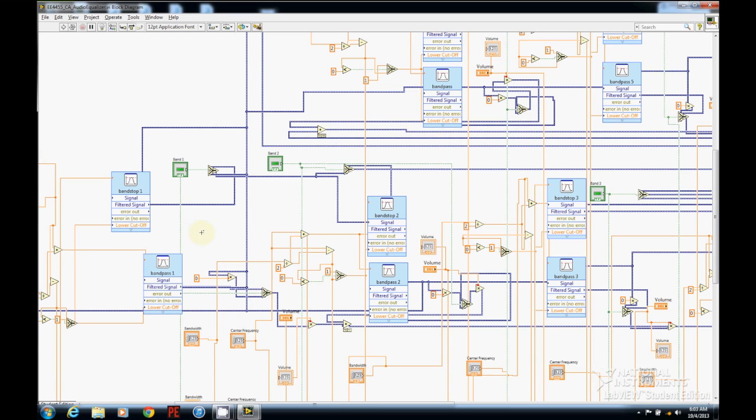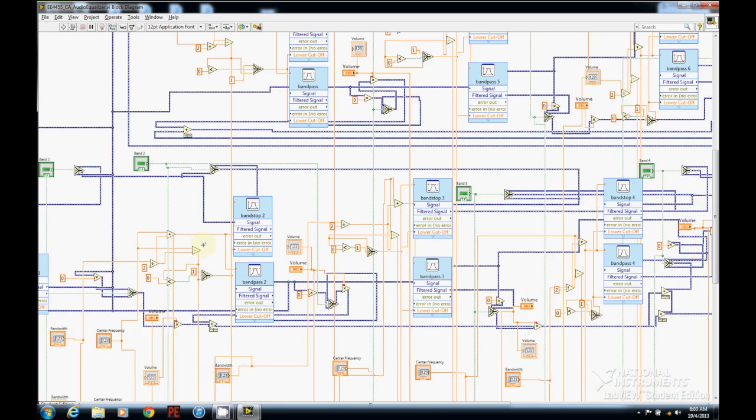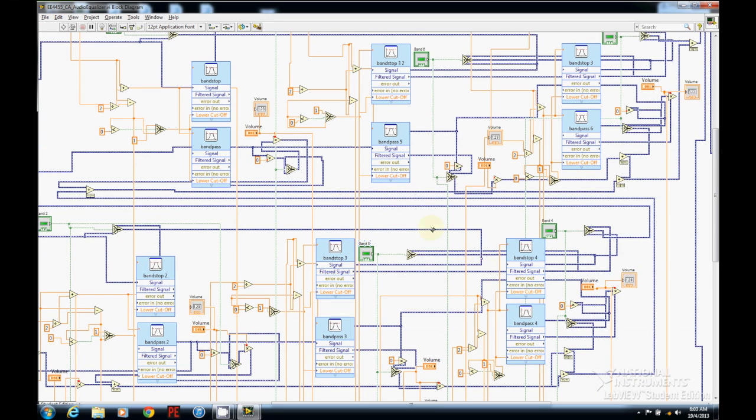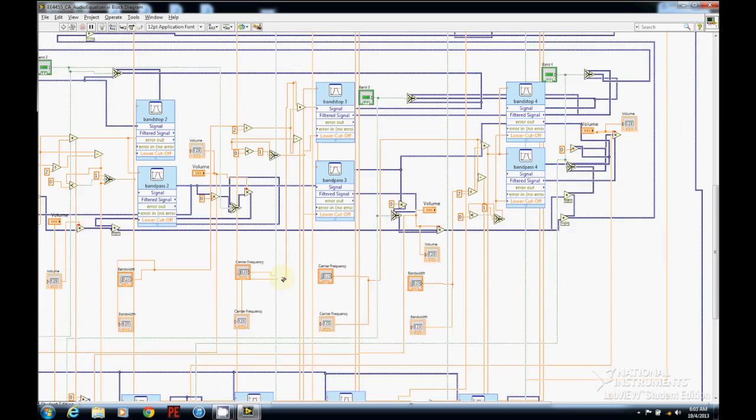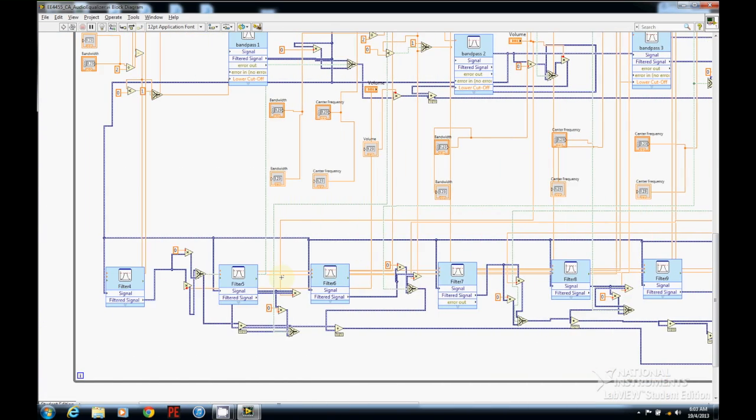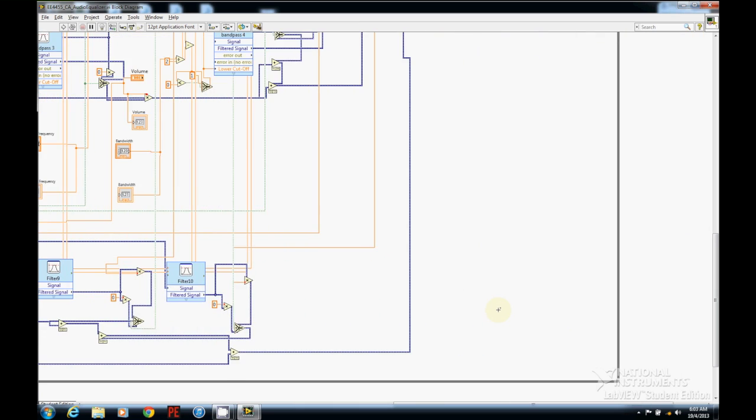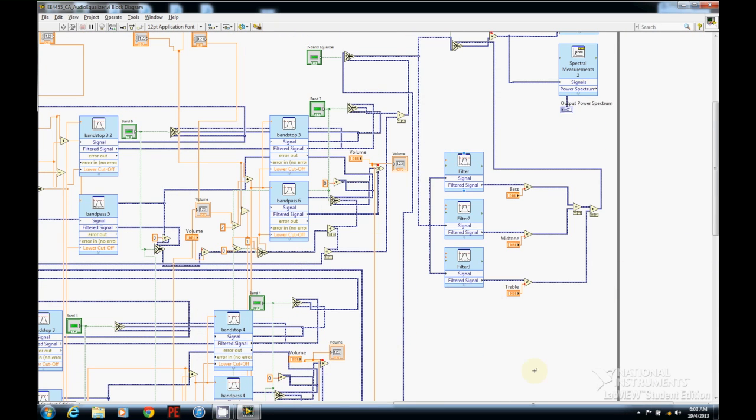The equalizer design consists of 7 bands made up of a set of bandpass and bandstop filters. Bandstop filters are implemented in a series manner to isolate the specific band from the original signal. Concurrently, in the parallel implementation, there is also a set of bandpass filters corresponding to their respective bandstop filters. These allow us to customize the center frequency, bandwidth and gain of the different bands. In addition, we have created another 7-band equalizer specifically to solve question 1.2 in suppressing broadband noises. Lastly, we have also kept the original 3-band equalizer from the reference document to fine-tune the audio signal.